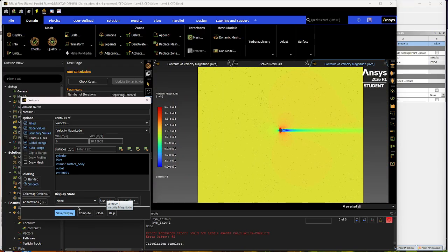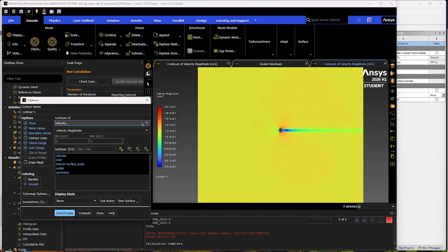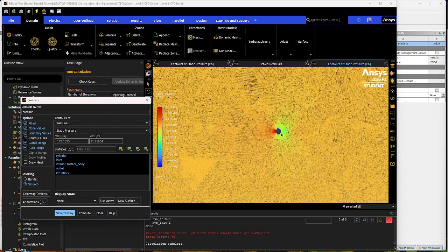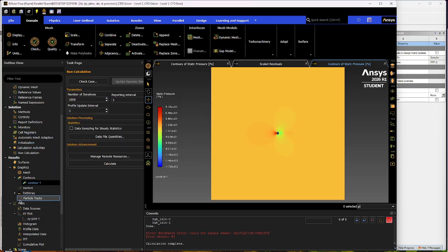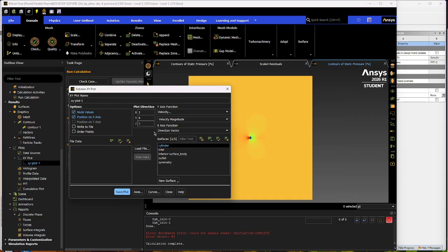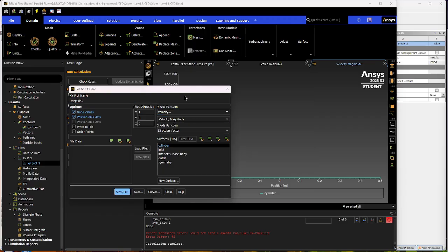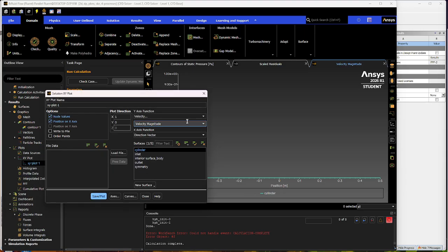And so we have that, and then again with the streamlines, you can do the pathlines and everything. Your pressure, you only need static pressure, so you use static pressure here, like that. And then lastly for the forces, so plot velocity, velocity magnitude. So this one should also be 0 because of viscous forces and the no slip condition. And then for pressure, pressure coefficient, save plot.